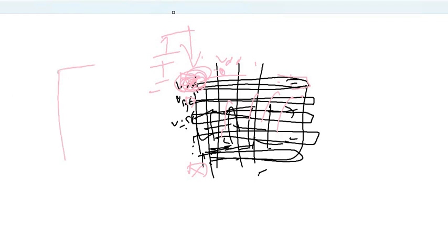And another good practice, what one should do is, whatever the pins are there, your routing should be touching the boundary here. Don't leave your pins dangling behind, somewhere in the middle over here. Okay, it is not the job of the next level person to keep looking for that pin. So your module, you're the owner, you need to provide proper access points. All the pins should come whatever direction you have decided based on your hierarchy. The pin should be at the edge. Always make a habit, because that's not the other person's job to keep looking for the pins internally and come and connect over here. Unless you have a talk with the person who is doing the next level module, then it is okay. But ideally, if you're the owner, it's always advisable to have the pins at the edges over there. Have a proper PR boundary, have pins at the edges. Okay, have a proper power mesh with the pins on the topmost metal.